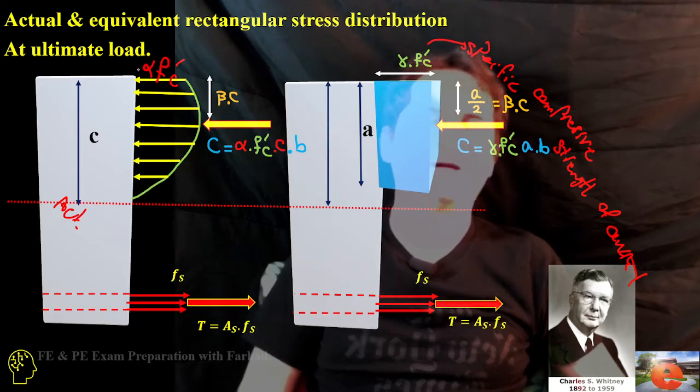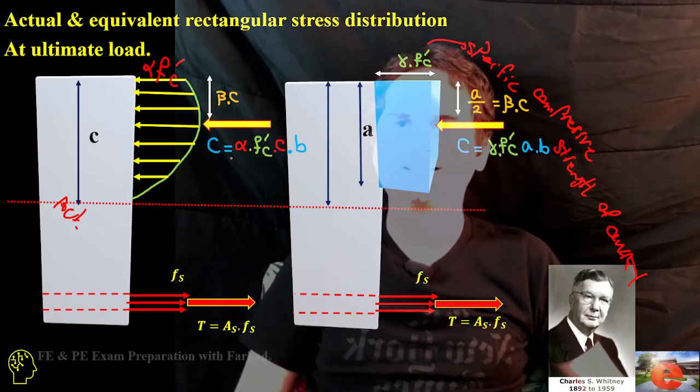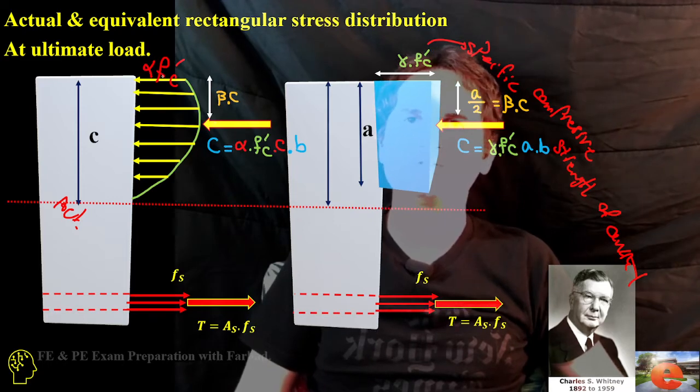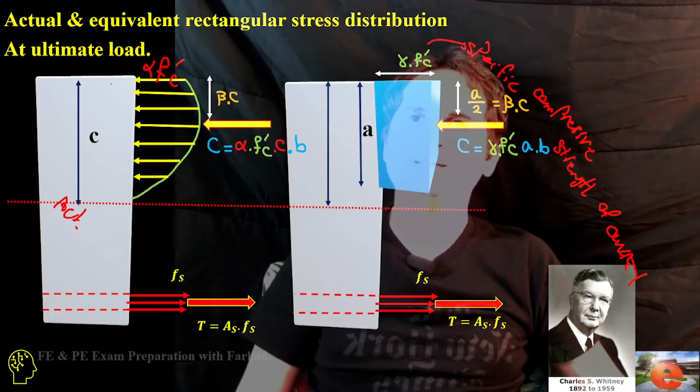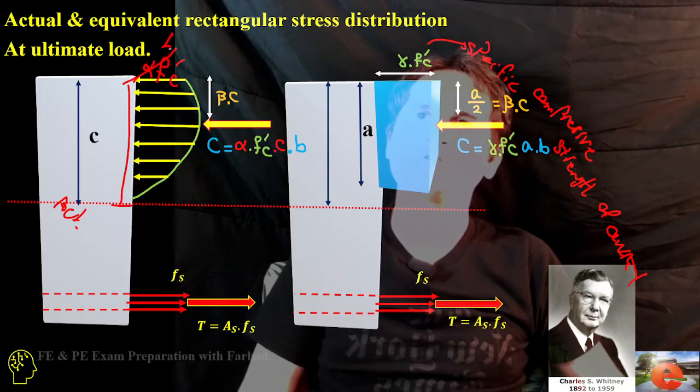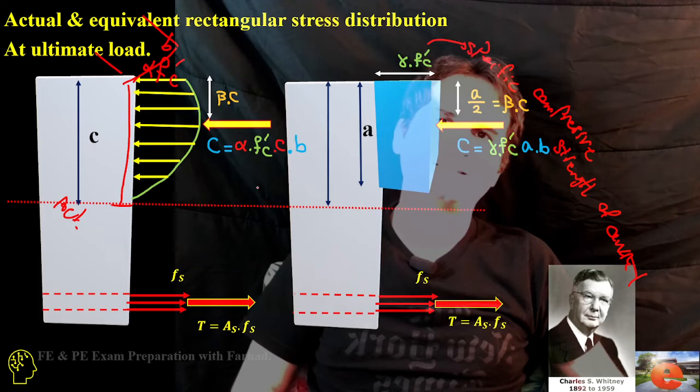So they have a coefficient for themselves. That's alpha F prime C, a coefficient times the specific compressive strength, times C, the distance to the neutral axis, times the other dimension, which is B. So that's the area.